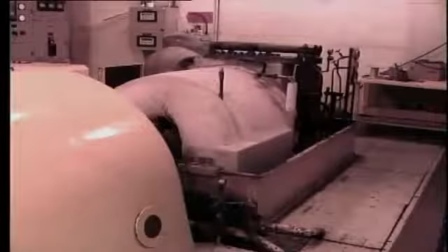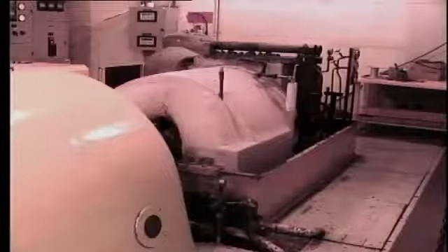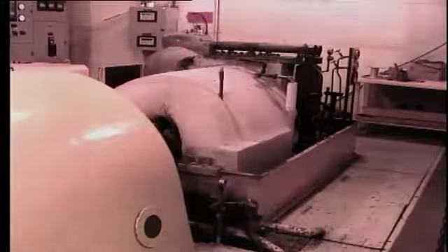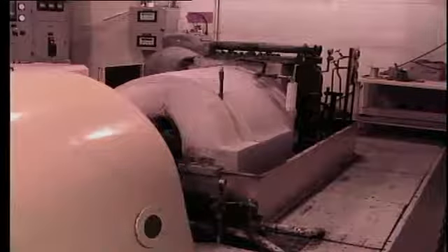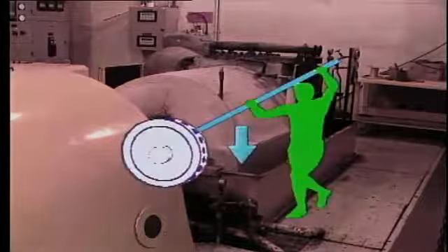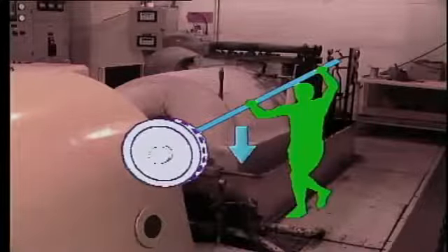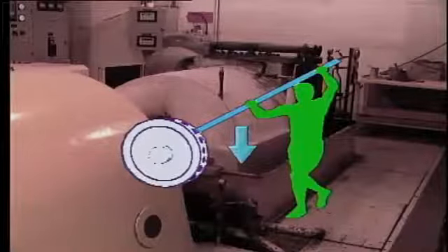Operation of the turning gear after shutdown is so important that in the case of a failure of the equipment, say a motor failure, then drastic action must be taken. One method adopted on smaller machines is to rotate the shaft by hand, if possible, say 180 degrees every half hour. On older machines, this was sometimes achieved by inserting a bar into the coupling. Thus, the first types of turning gear were often known as barring gear.